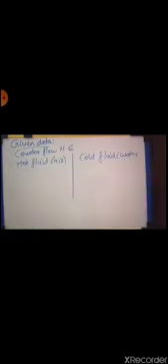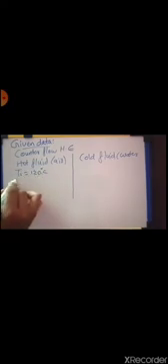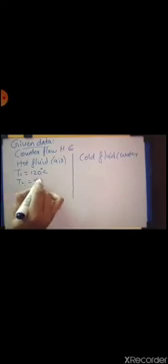It is a counterflow heat exchanger. Hot fluid is air. The inlet temperature of hot fluid air, capital T1, is 120 degrees centigrade and capital T2 is 50 degrees centigrade. Considering the cold fluid, that is water, inlet temperature small t1 is 10 degrees centigrade and outlet temperature of cold water small t2 is 25 degrees centigrade.